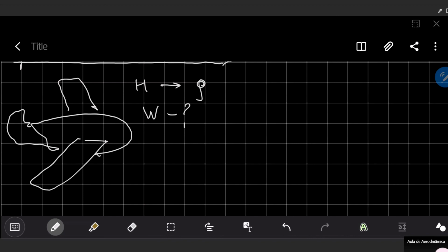Also, this airplane probably will have a size. I will show you the length of the wing, right? This wing also has some chord, size C. So when we know the length of the wing and the chord size, we can calculate the planform area, which is composed of two wings. So the area I will write here is 2 multiplied by L and multiplied by your chord.